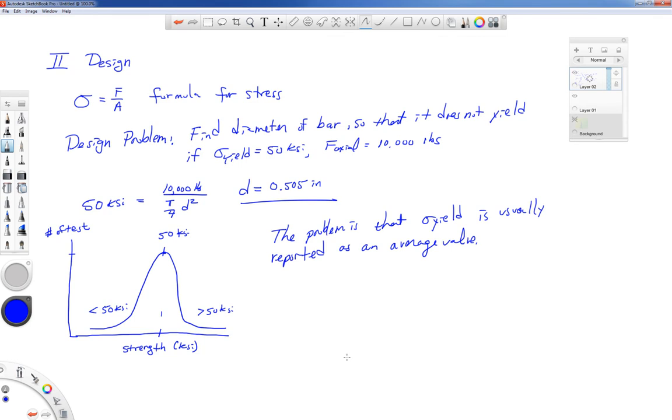So, for example, an automotive company will take and they will instrument a vehicle and they will let a customer drive it, and they will measure the door slams, how hard the door gets slammed, how big of potholes the car goes over, what loads are induced in the suspension when the car goes over a pothole. And they will collect all that information and they will do statistics on it, and they will come up with usually a very severe representative customer, what they call sometimes the 99th percentile severity customer, and they will design their structure to that 99th percentile level, or it could be 99.9th percentile.